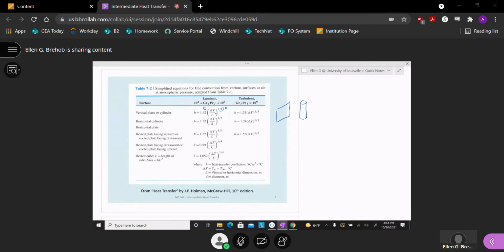This is not the way Incropera and DeWitt, now Bergman and Lavine, our book, does things. They don't show this. It was a little bit new the first time I took a look at this, but I think it's kind of interesting. Again, it holds for just a very particular case of air at atmospheric pressure, but we see that case pretty often. It also brings out the idea that for laminar flow, this exponent is different.